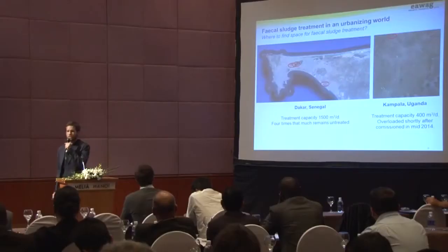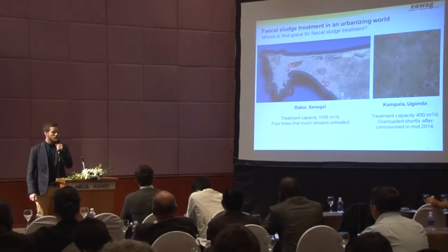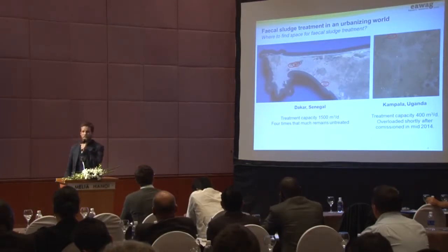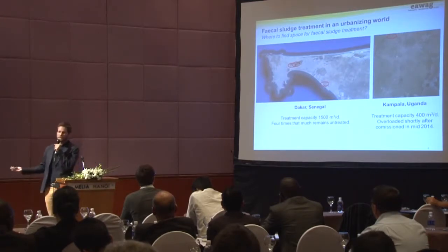As you know, fecal sludge is mostly water, so one of the main steps when treating fecal sludge is separating liquids and solids. Drying beds are commonly used all over the world. They have the advantages of low operational and low capital costs. They benefit from the semi-arid climate in sub-Saharan Africa, but a big disadvantage is they need large drying spaces.